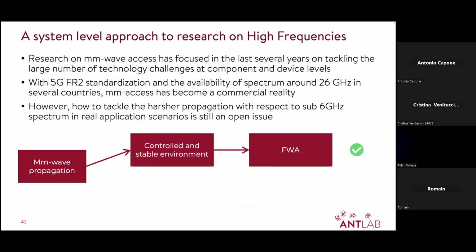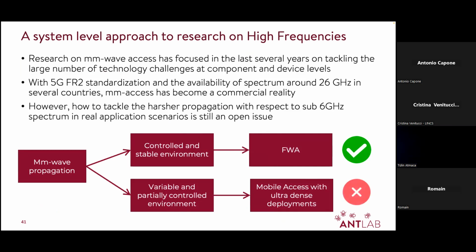The discussion on millimeter wave access started more than 10 years ago with the standardization of 5G. And actually with Stefano, we have been involved in one of the first projects on millimeter wave for 5G. It looked like something very easy, right? When technology is getting mature, it will be deployed in the network easily. The truth is that it has been deployed only for fixed wireless access. Why? Because in that case, the propagation environment is controlled and stable. You control everything with planning, and once you deploy the network, unless you have a new building in between, everything is controlled and not changing.